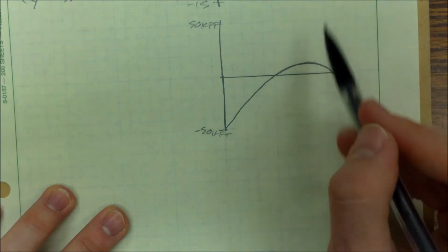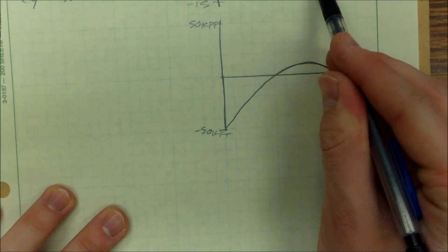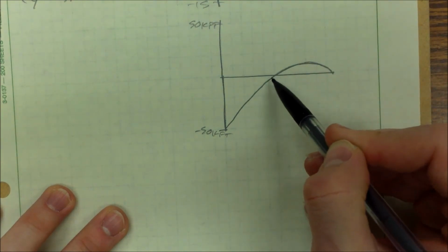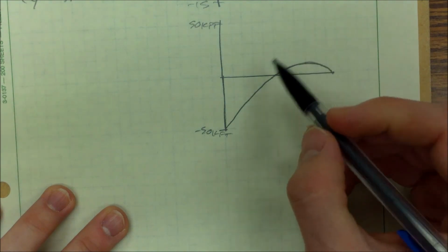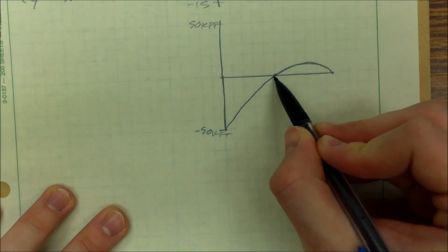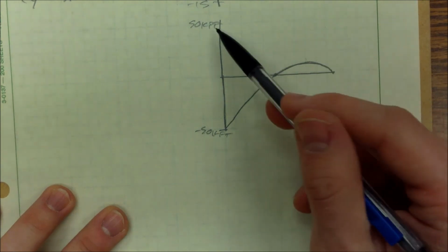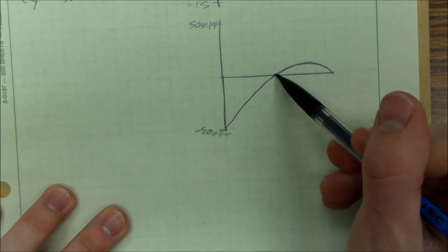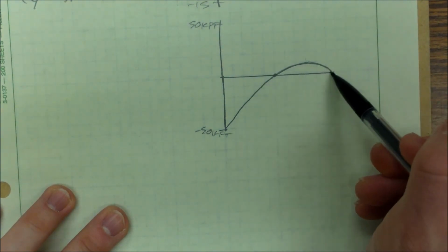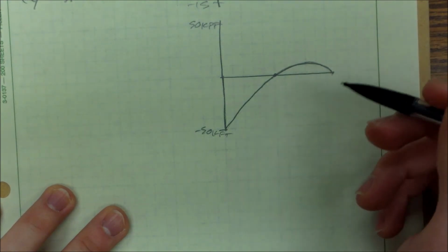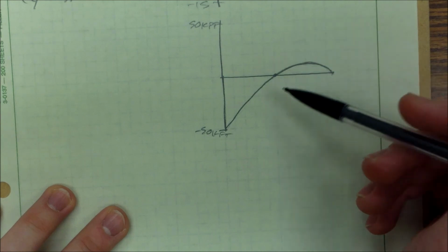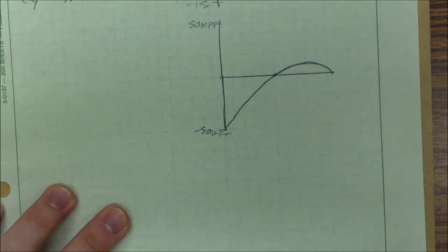And I know that it's going to peak right where the shear is 0. And as I thought it would, the hinge ends up being right where the moment is 0. And this is always going to be the case. On my moment diagram, wherever the moment crosses at 0, that's where my hinge was, if I have a hinge in that problem. Alright, and that concludes that problem.